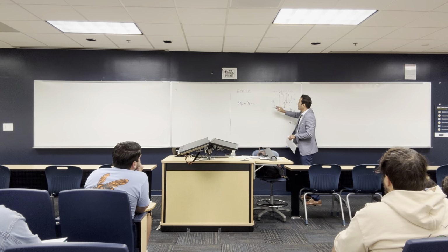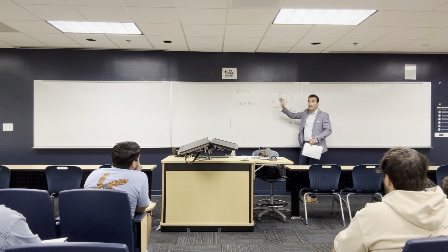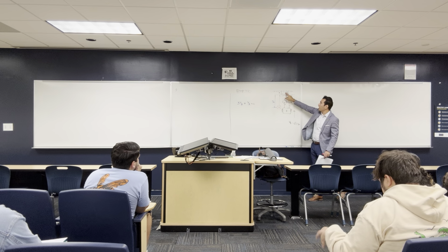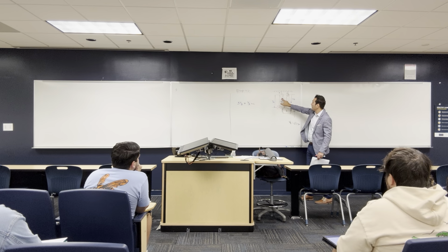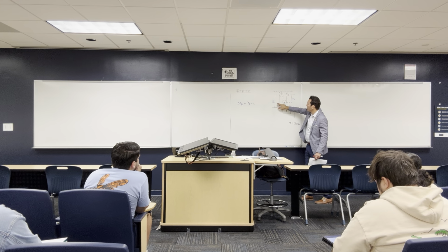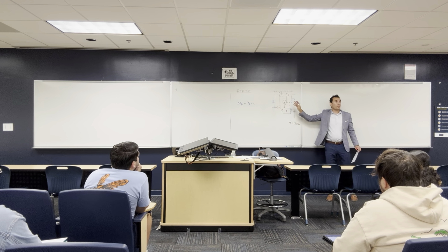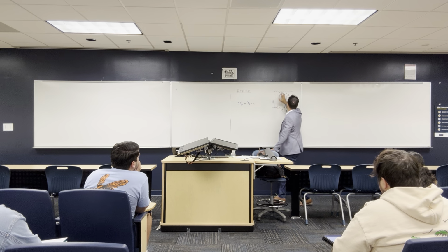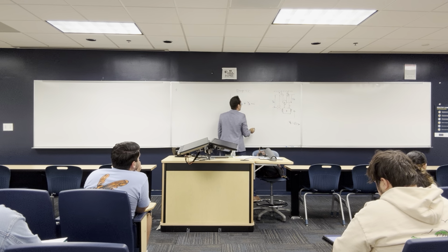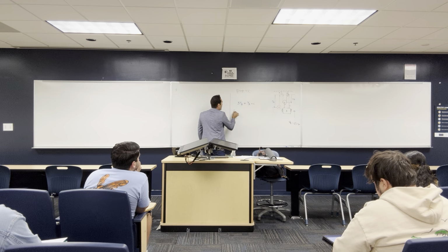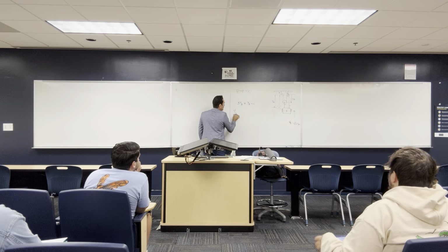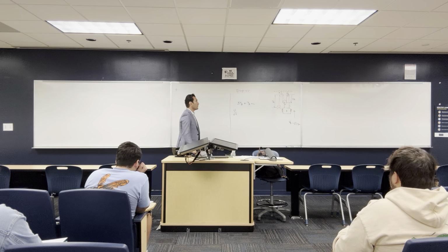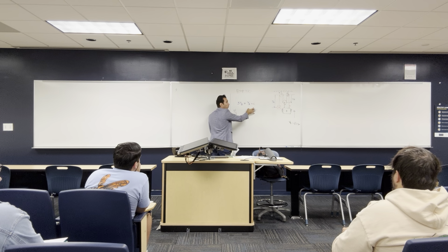and L4. And you can put them here in this equation and say that L1 plus YB plus L2 plus YB plus L3 plus YB plus L4 plus YA is equal to the length of the cord. But all these lengths are constant, like L1, L2, L3, L4 are constant. It's not gonna benefit me when I take d/dt of this equation, because they all are gonna be 0 because they are constant. I'm only interested in the variable lengths.